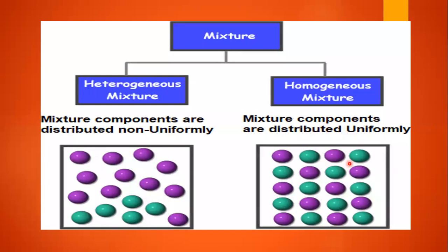And what is the equivalence ratio? The equivalence ratio is nothing but the actual air fuel ratio divided by the stoichiometric air fuel ratio. What is the actual air fuel ratio? It depends upon the engine speed. Depending upon the engine speed, we need to take the required amount of air fuel mixture.